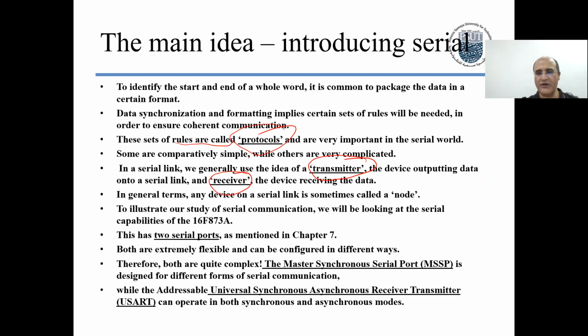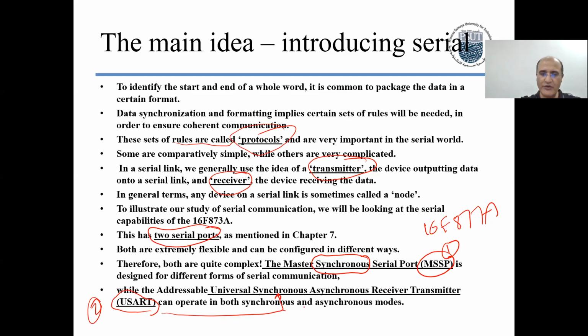The 16F877A controller we are using has two serial ports. One of them is called MSSP, which stands for Master Synchronous Serial Port, and it is a synchronous port, so we're not going to deal with it. The other port is the USART. USART stands for Universal Synchronous Asynchronous Receiver Transmitter. This can work in either synchronous or asynchronous mode. We're going to use it, but in asynchronous mode.